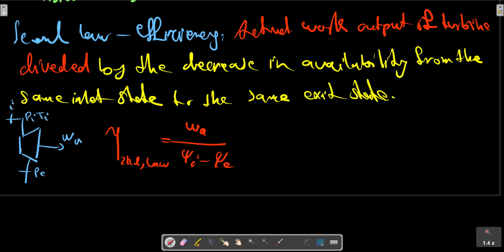In this sense, these concepts provide a rating or measure of the real process in terms of the actual change of states. In simplified form, it is another convenient way of utilizing the concept of thermodynamic availability. In a similar manner, the second law efficiency of a pump or compressor is the ratio of the increase in availability to the work input to the device.